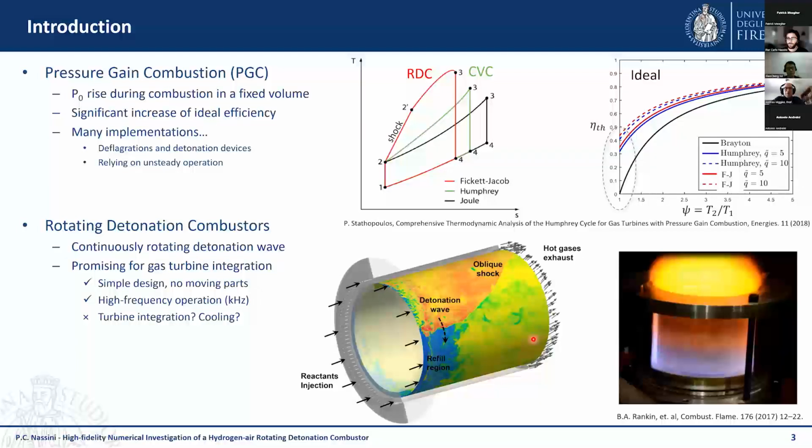Just think about a shock wave going by you. Yes, there's an increase in pressure and an increase in velocity. So if you compute the stagnation properties, I guess it would increase, but you have to be very careful with the interpretation of that. A fundamental thing in thermodynamics is total pressure is an inverse measurement of entropy. So from that reasoning, a shock wave would be a very magical wave. It would go by and spontaneously decrease the thermodynamic entropy, which would violate the second law of thermodynamics. So I would caution you from starting your talk with a sentence that implies you found a way to violate the second law of thermodynamics.